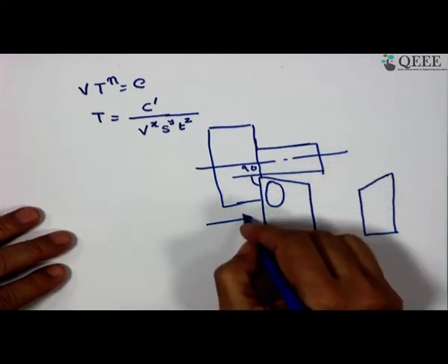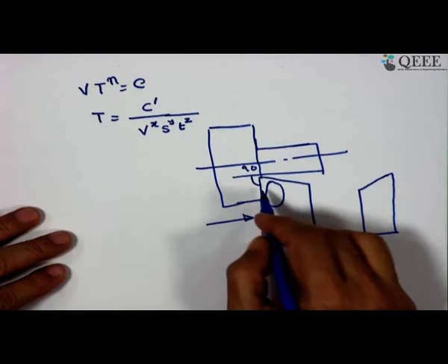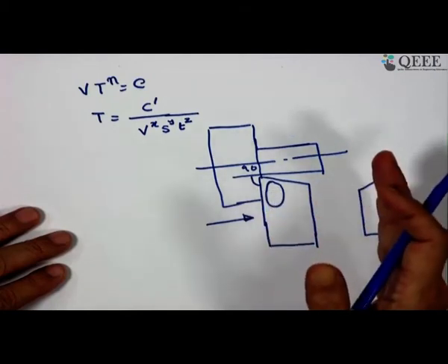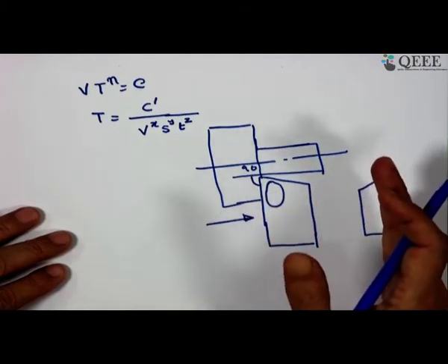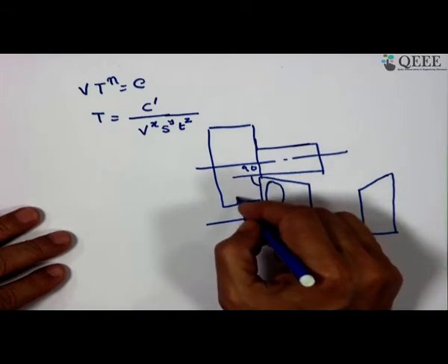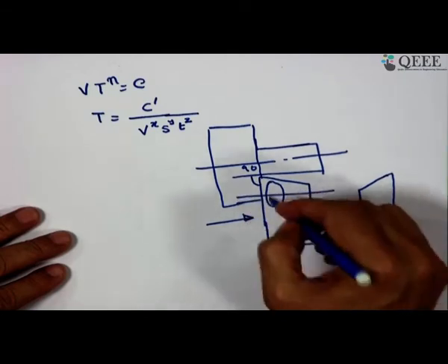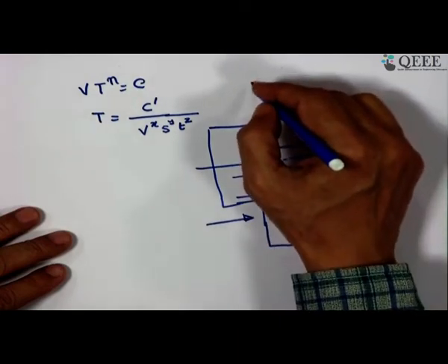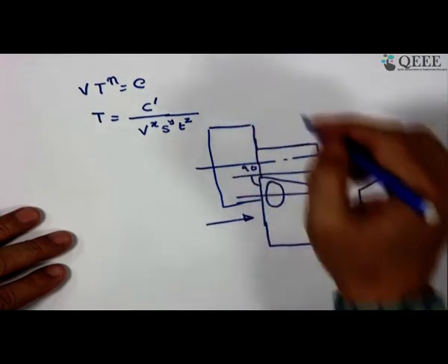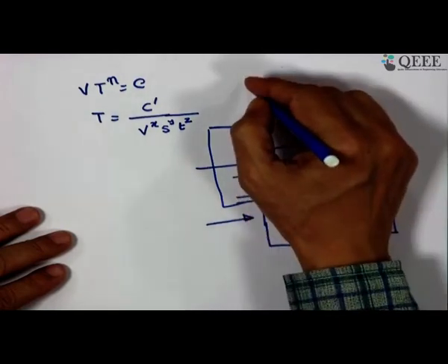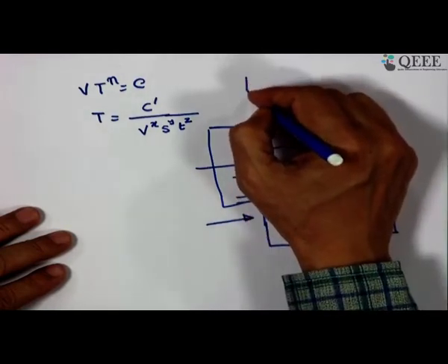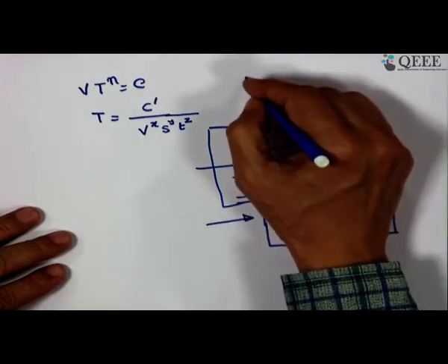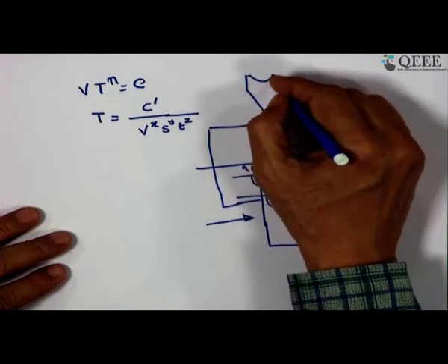That means, looking from this side, the view on the y plane or on the cutting plane, and if you take a section on this side, it is the orthogonal section, and if you take the tool here, what we reasonably see is the flank wear, then you have the clearance, and then you have this cavity.